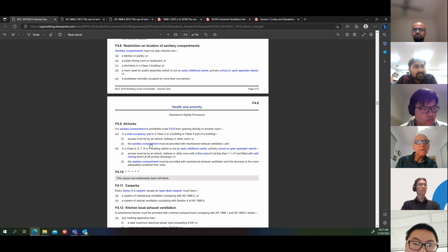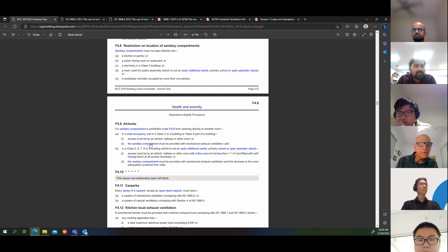Just the client needs to be aware that if it's a hot day or a cold day, and they want to close the windows and they get a full house, then they may not be complying with AS1668 Part 2 or the NCC. So you've got to use a bit of judgment, common sense, I suppose, that if you're satisfied that it's feasible and can operate that way, I think you can do that. But just be careful that you're covering the requirements in all modes.